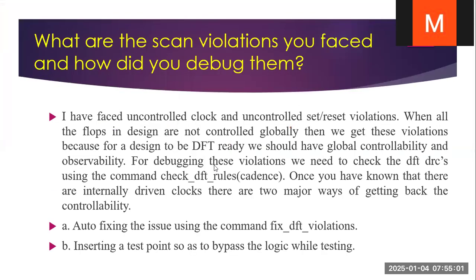Next, what are the scan violations you faced and how did you debug them? I have faced uncontrollable clock and uncontrollable set/reset violations. When all the flops in the design are not controlled globally, we get these violations, because for a design to be DFT ready, we should have global controllability and observability. For debugging these violations, we need to check the DFT DRCs using the command check DFT rules.